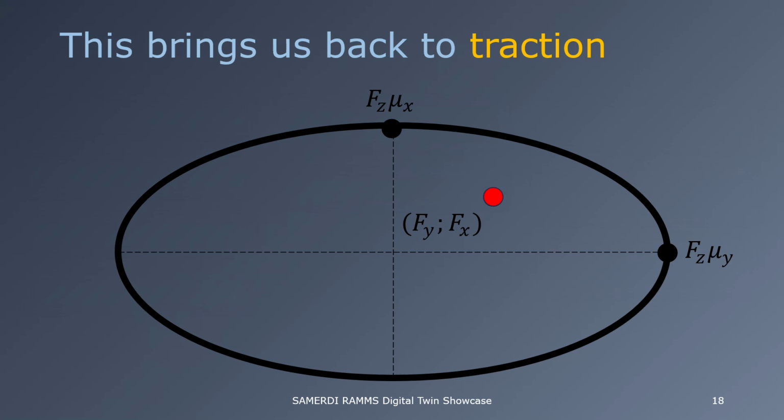So firstly, let's quickly discuss the concept of a traction ellipse. This ellipse defines an envelope of traction that each wheel experiences. All right. And then this red dot defines the current traction that has been used up by a certain wheel. So when the current traction exceeds this envelope, that is when a wheel is expected to slip. All right. So firstly, how do we define this envelope?